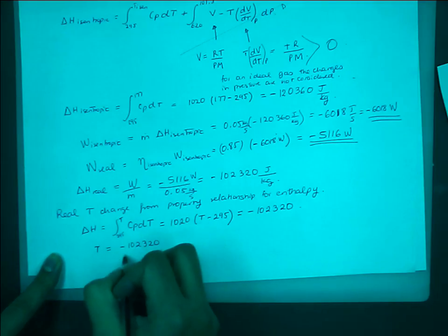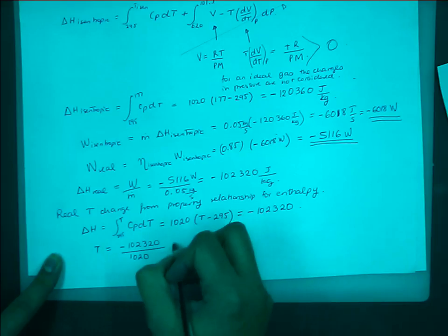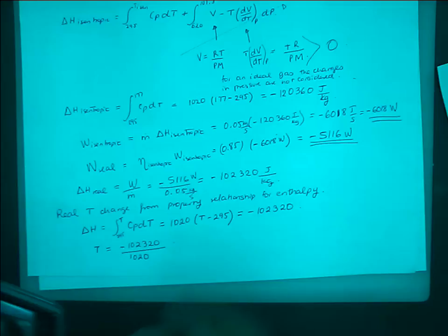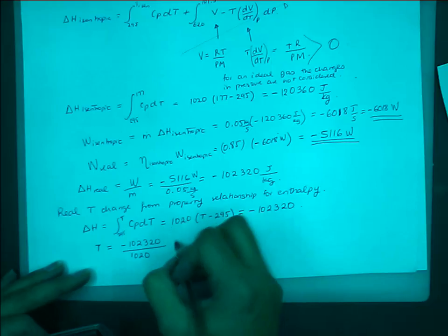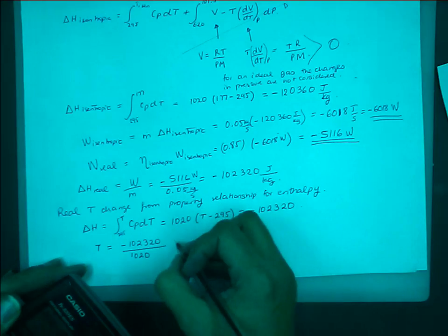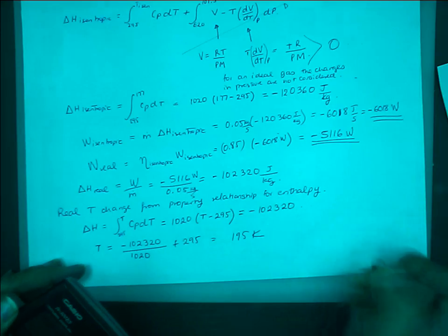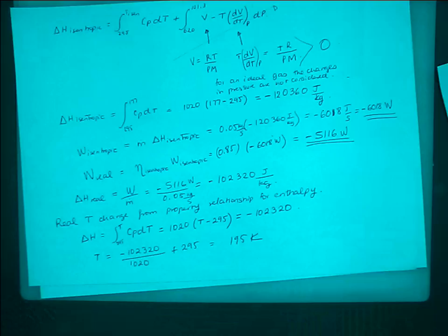Right? It's more or less the same way, but we only need to consider how the equation works to work out from W isentropic to W real, and just check that this temperature will actually be lower than the inlet one, so that is fine.